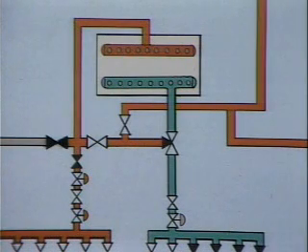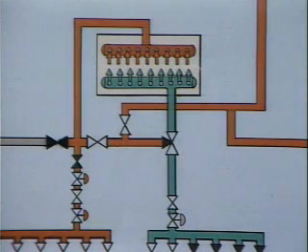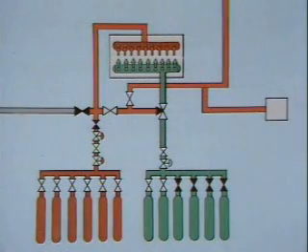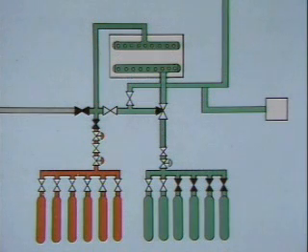The CO2 enters the generator through a manifold at the bottom of the casing. The heavier CO2 forces the hydrogen back through the upper manifold. From there, the hydrogen passes through the vent pipe to atmosphere. Outside, large quantities of air dilute the hydrogen safely.